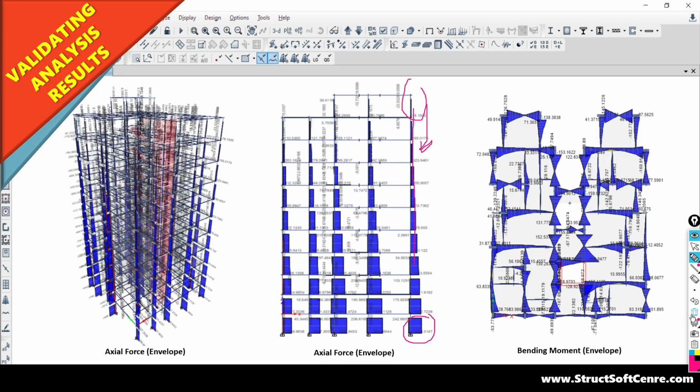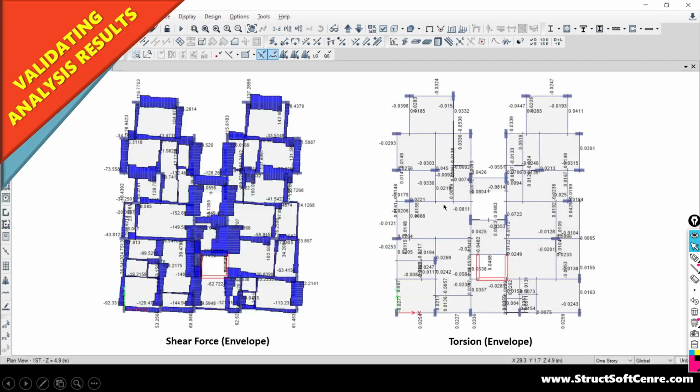we have to look at the response of the structure under the gravitational load, meaning deflection, under the lateral load the deflection, and the stress distribution in your floor slabs. The diaphragm concept you have to implement here, because your structure is going to be subjected to lateral load. That diaphragm concept we are going to deal with in detail in our advanced level. So this part is also going to be covered, and this is about shear force and torsion.